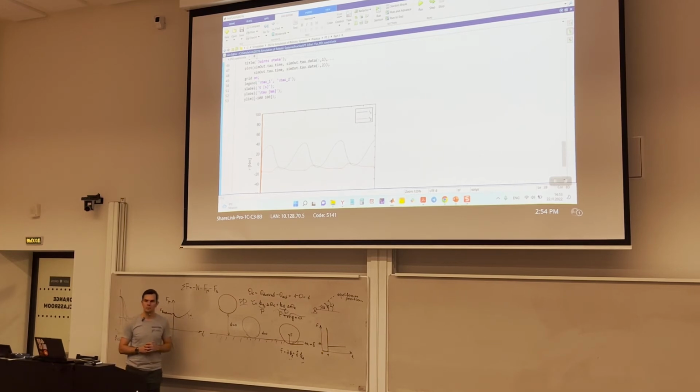What's the desired motion? Any trajectory. Let's assume that we do some kind of motion, and suddenly we put an obstacle. What will happen? It will constantly generate forces because the error will be constant, but the controller doesn't understand that there's an obstacle.